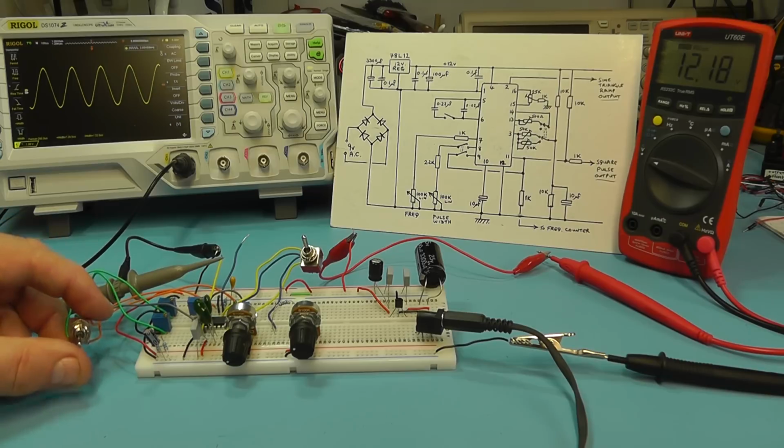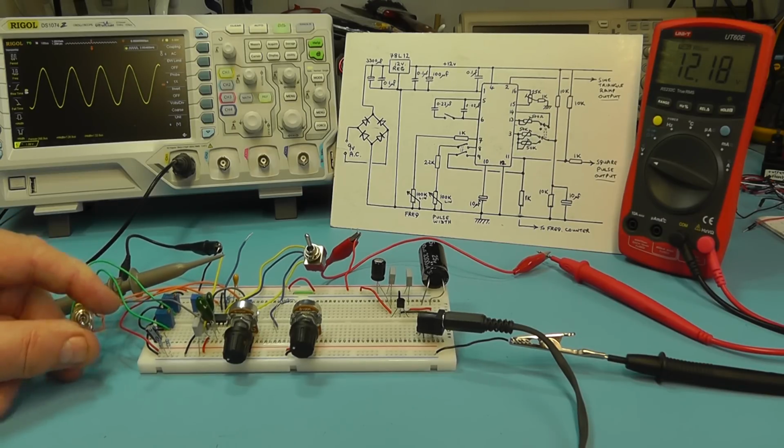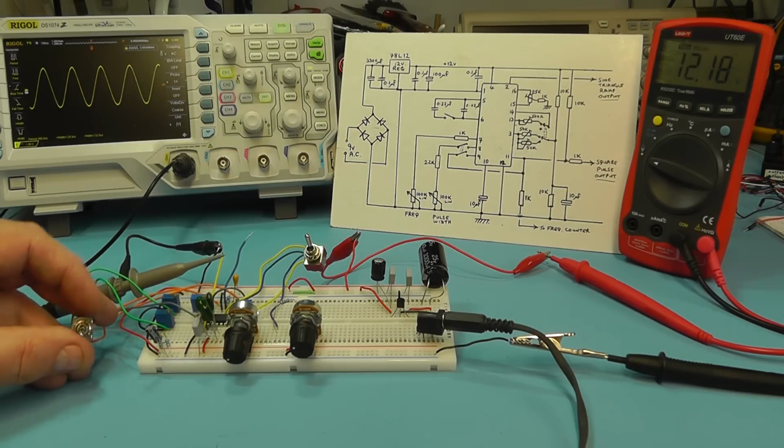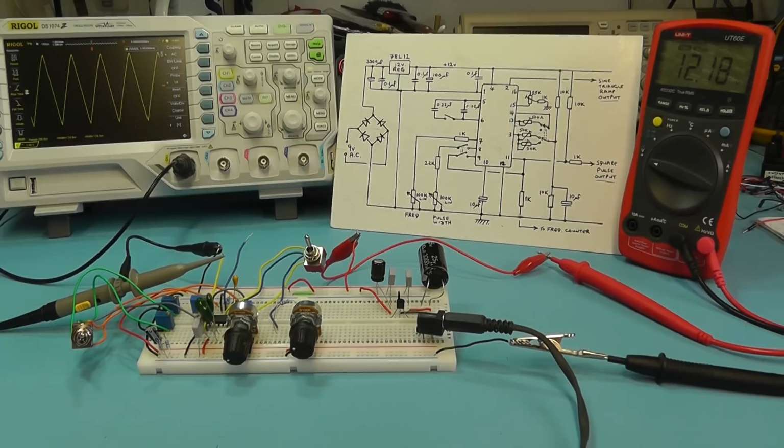You see there's quite a difference between the two, and that's the reason, under normal conditions, that's the way the circuit will normally work, and that's the reason I've actually put two little gain pots in here rather than just one. On normal circuits for this particular chip they seem to just use one little preset. What I've done here by using two and switching them in alternately, one for sine and one for triangular waveform, we can balance out the differences in the amplitude to get them more or less the same.